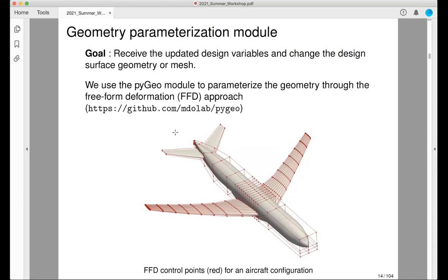I think this is a very important step. By the way, the reason I want to mention all these modules is that in the DAFoam run script, we need to provide the parameters and setup for all of them. So it's necessary to explain the input and output of each module and how they work.